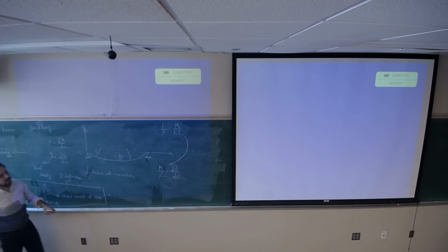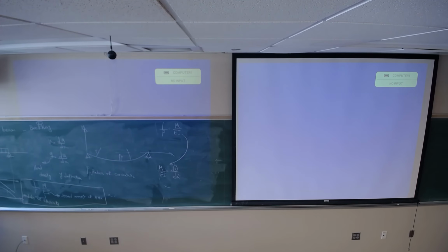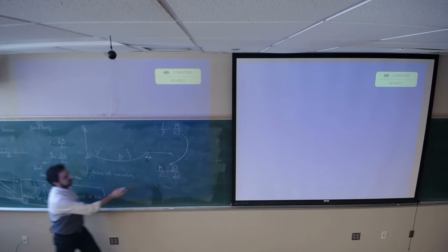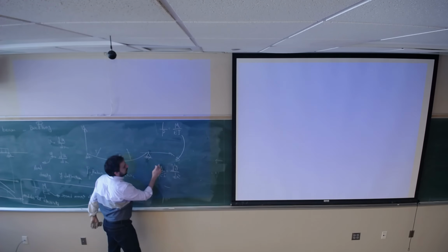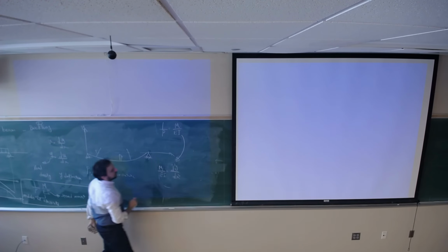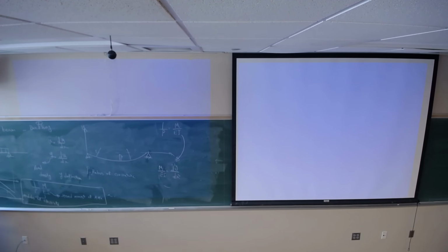It's not a difficult proof, but since the equation is long to write on the board, I just skip the proof, and you don't need to be worried about that. But we can prove that the bending moment divided by EI is going to be the second derivative of y, which is the deflection, with respect to x.